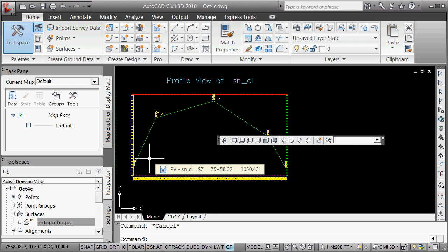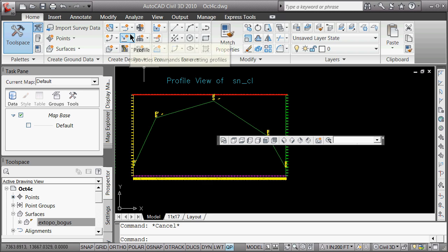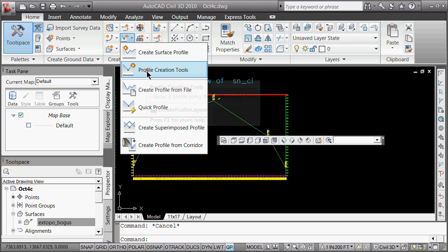So we're pre-planning to get close, at the very least, at any points where we have intersecting horizontal alignments. That would be the case unless we were doing flyovers or underpasses or something like that, which is not as big a deal now that the Olympics are not coming to Chicago, but I still presume there'll be a fair bit of work in rail corridors in the next 5 to 10 years. The term you're going to hear for this kind of splitting up of the grades is grade separation. But in this case, we're not going to grade separate.